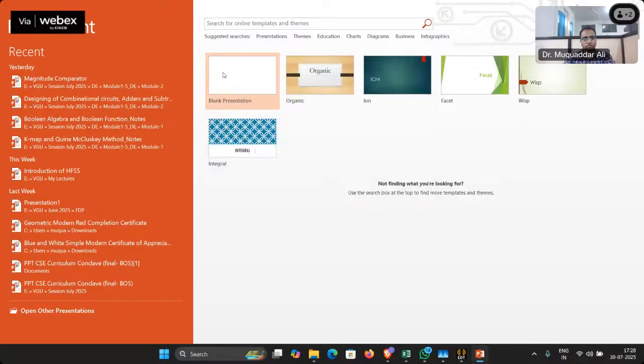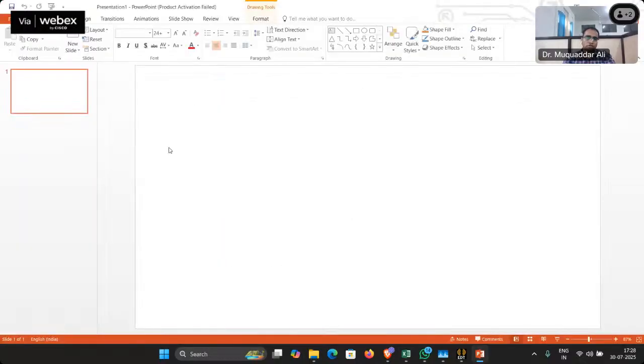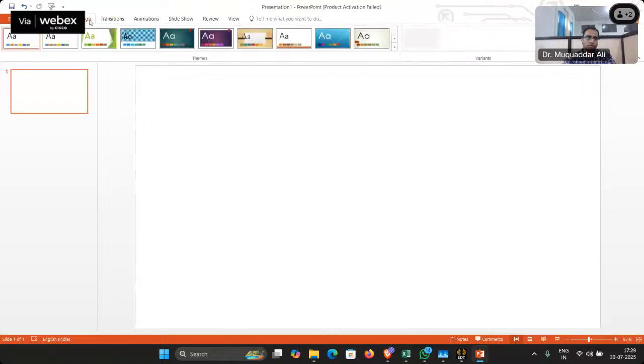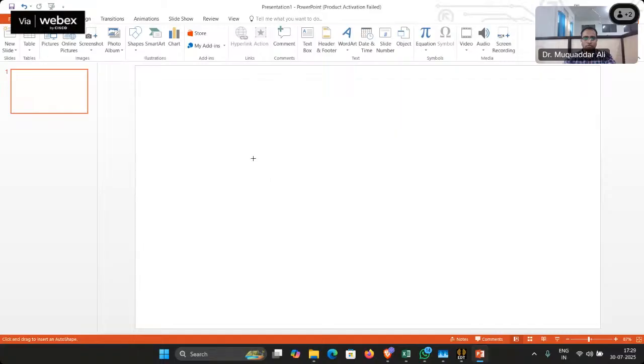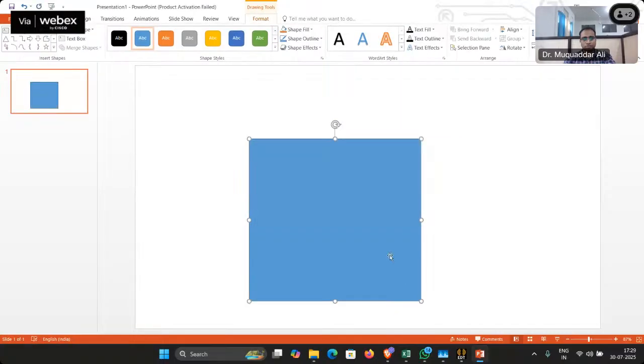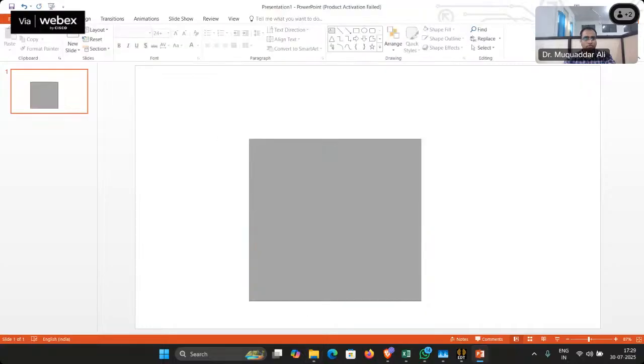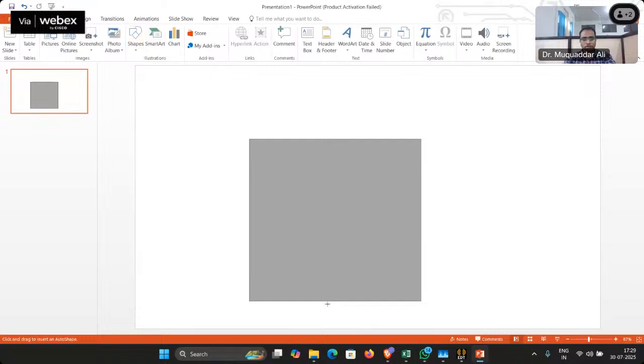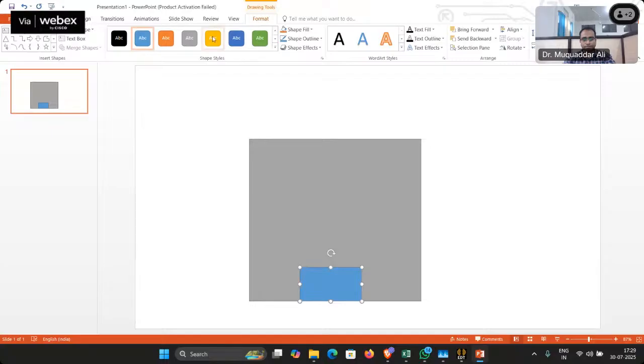So in order to create this with MIMO, what we need, let me show you, for example, we have a substrate here, and now again, on this substrate, in this portion, we have an antenna, and we want to add one more antenna on the same surface. We can place it here, we can place it here, or we can place them like this. So all this geometric variation depends on your device type.